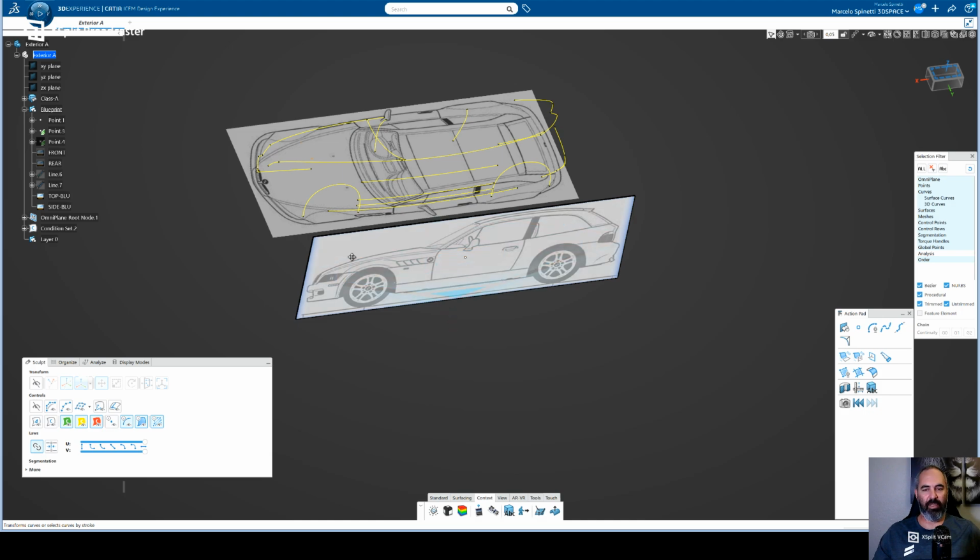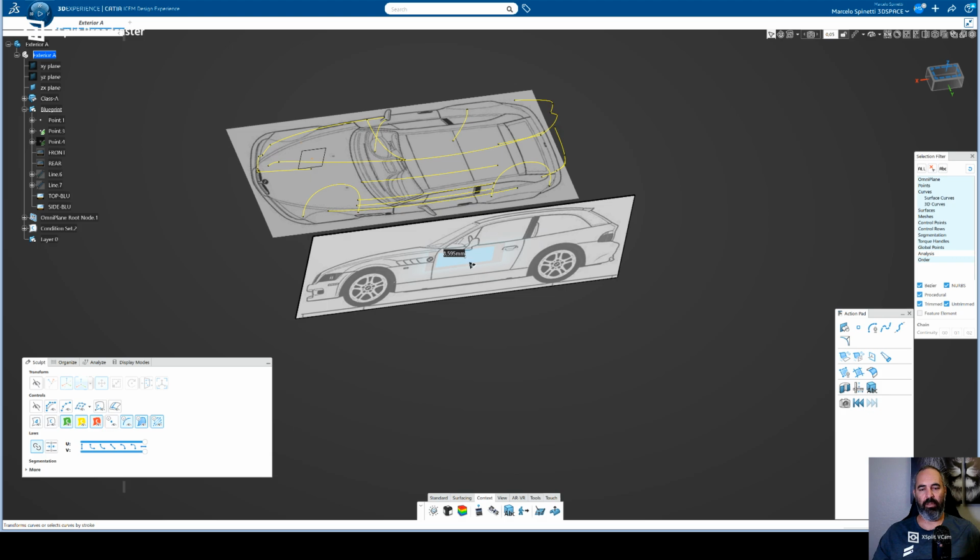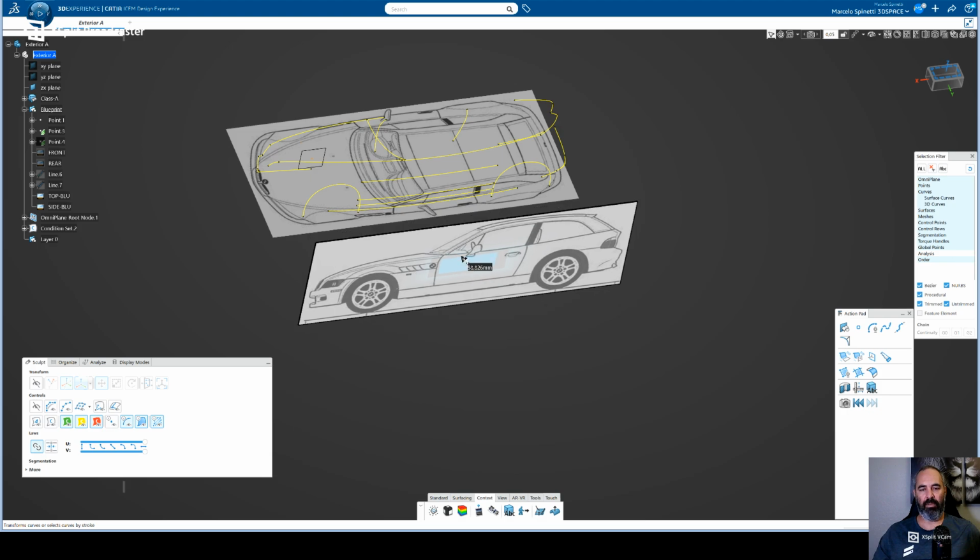This is a trick that Nick shows also. We have to show first the plane. You see that there's a plane here, no, not XY, XZ, sorry. XZ plane. Okay, XZ. So I click twice here. Now I click the center. This is the plane where I move it in the plane of the image.